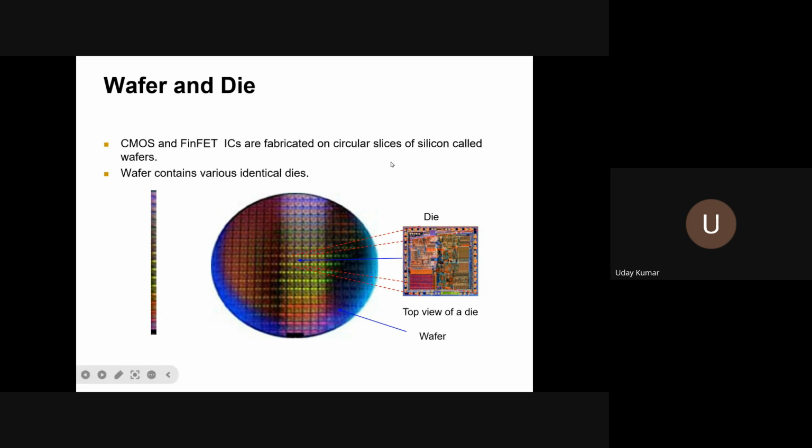So, the thing is, while preparing these dies, there will be a process where this particular slice has to rotate at some thousands of RPM for uniformly distributing the dopants. They'll try to put the dopants in the center, and to maintain the doping concentration uniform, they'll rotate it at some thousands of RPM.